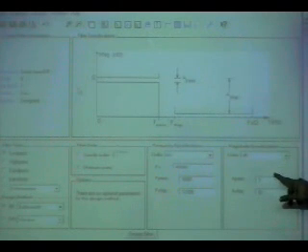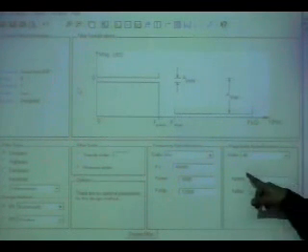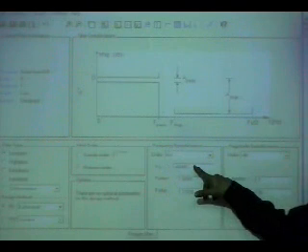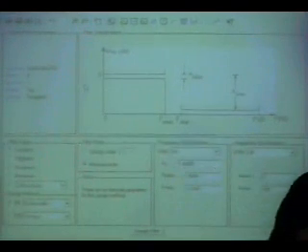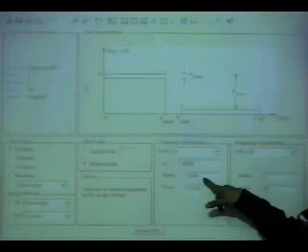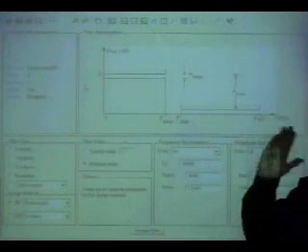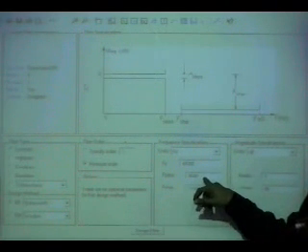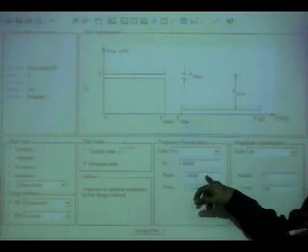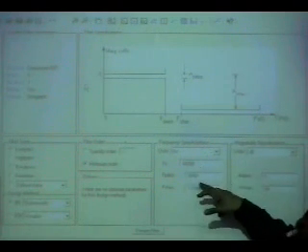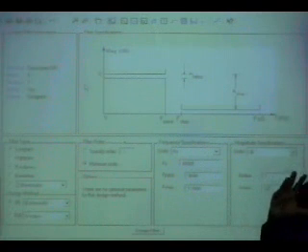This is delta 1 and this is delta 2, 1 dB and 80 dB. This is the sampling frequency, because it's better that you give the sampling frequency, and in relation to it, it is 2 pi. Then the F pass, the frequency you want to pass, corresponds to omega p, but it is given in hertz. People prefer that because they know the sampling frequency, they prefer to use hertz, though it's a digital frequency.